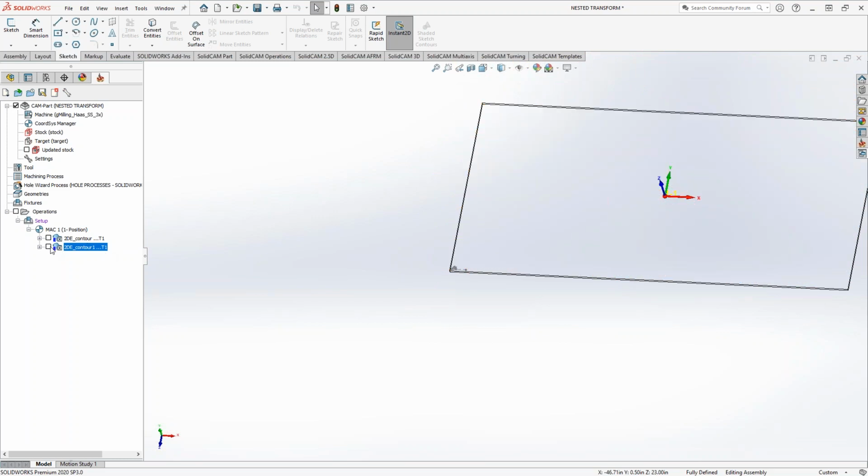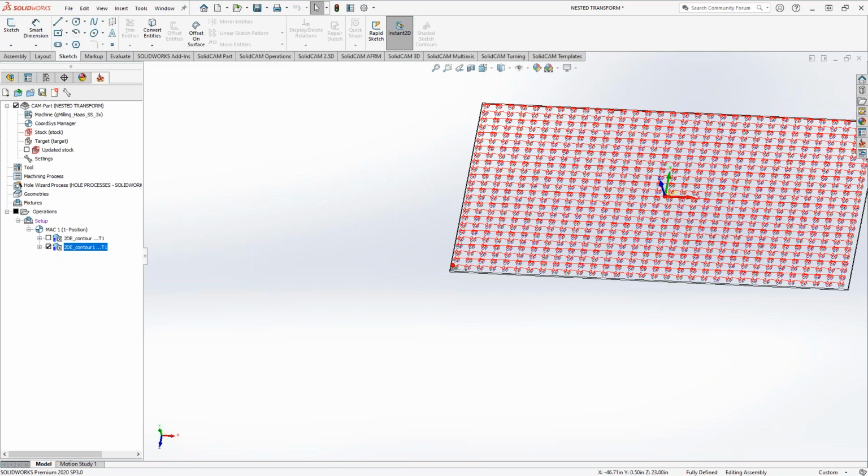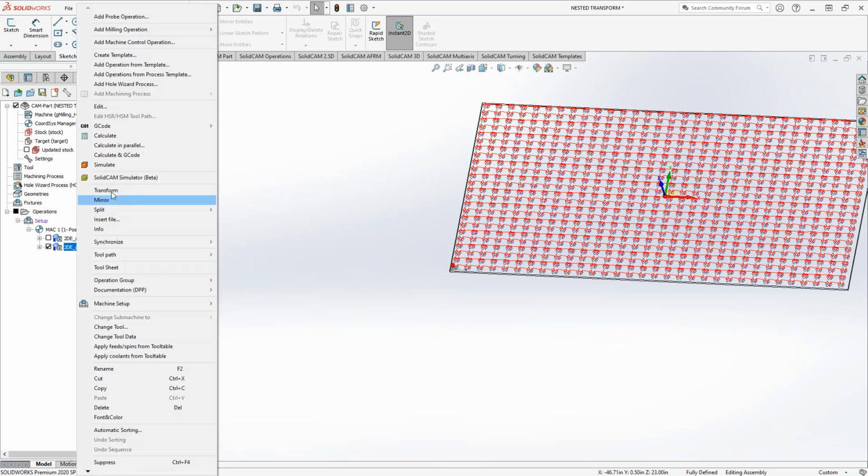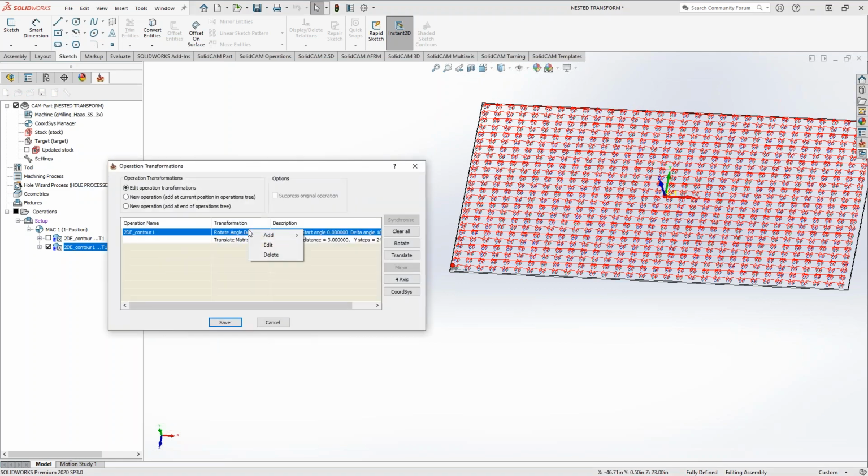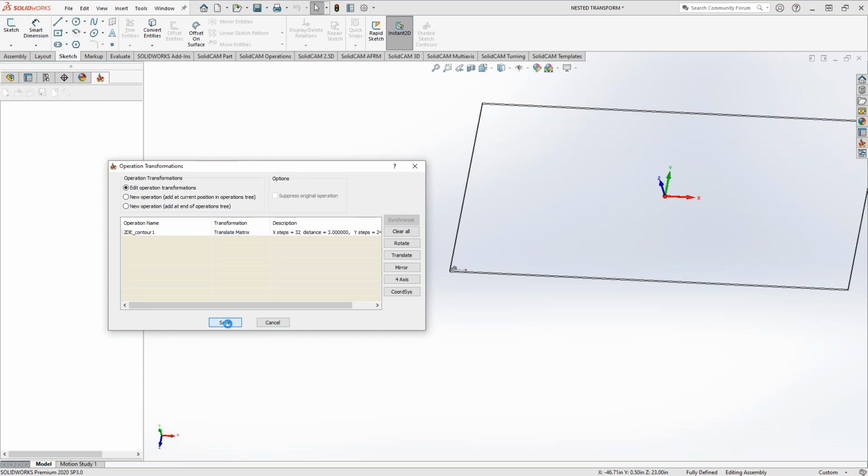Okay. And for anybody else that's on here, this SolidCAM does not have nesting built in. What nesting is, you give the software a part, multiple parts, or just one part, and it will fit as many as you can on there. But this is the next best thing. Like Mark was saying, you only have to program this part one time, and then we can make copies of it that many times in X, that many copies in Y.